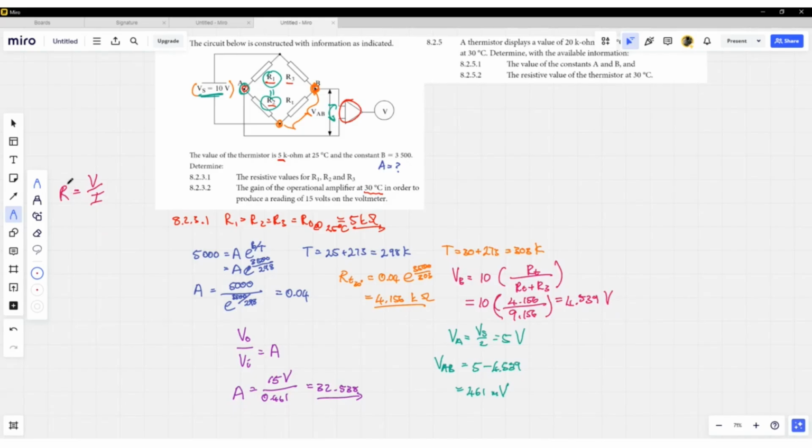If we plot the resistance as our y-axis component and the current as our x-axis component, you can see there's not a linear relationship. You end up with a non-linear relationship with one of the quantities that you want to measure. So basically what the Wheatstone bridge does is linearize that non-linear relationship.